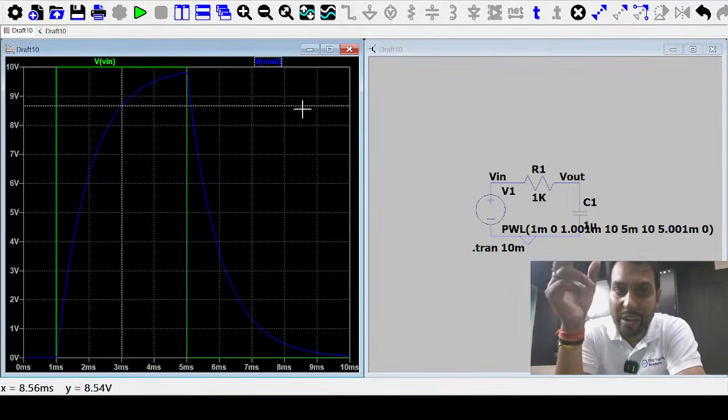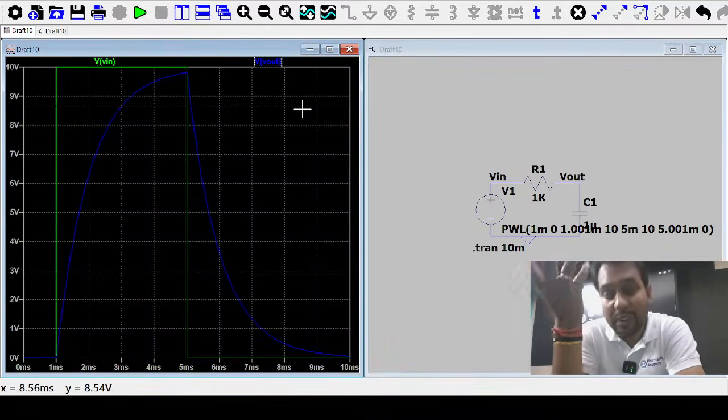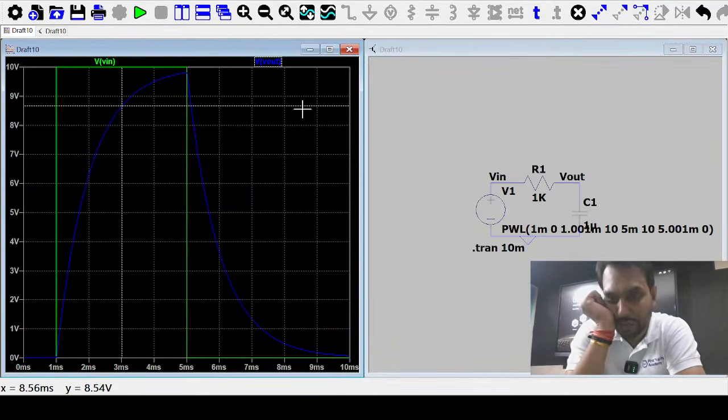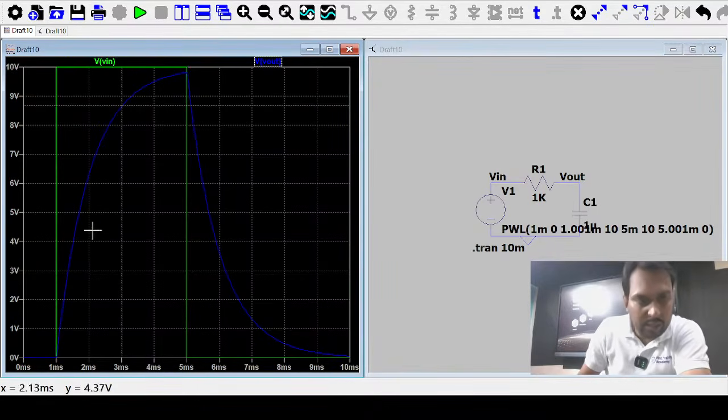I gave an idea that you use an RC circuit, but generally this RC is not linear, it is non-linear. Going from 0 to 5 volt it takes a different time than going from 10 to 5, because it is exponential, not linear with respect to time. So if you understand my question, please solve how you can make this linearized. So this is the question.